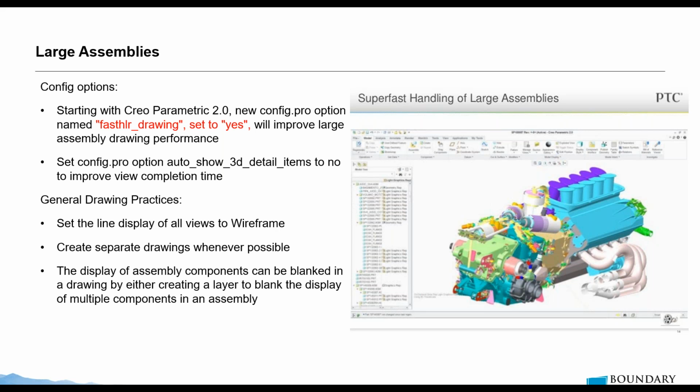So I would have one drawing file with maybe 1 or 2 sheets for my major assembly, the top level, and I will maybe break down 1 or 2 sub-assemblies from there. Then I will have a drawing for a sub-assembly as well, and a drawing file for each of my components as well.